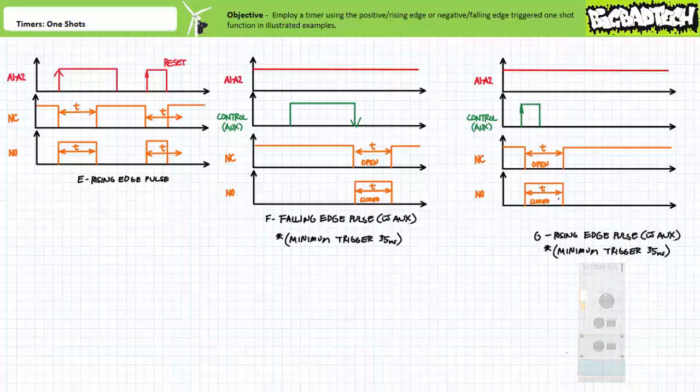Troubleshooters take note. A multifunction timer executing the right function at the wrong time needs to have the delay adjusted. In contrast, a multifunction timer executing the wrong function at the right time needs to have the function adjusted. I'd like to say a misinterpretation of functions is a rare occurrence, but it isn't, and you need to be aware of this possibility. Let's now move on to the remaining topics of this lecture.